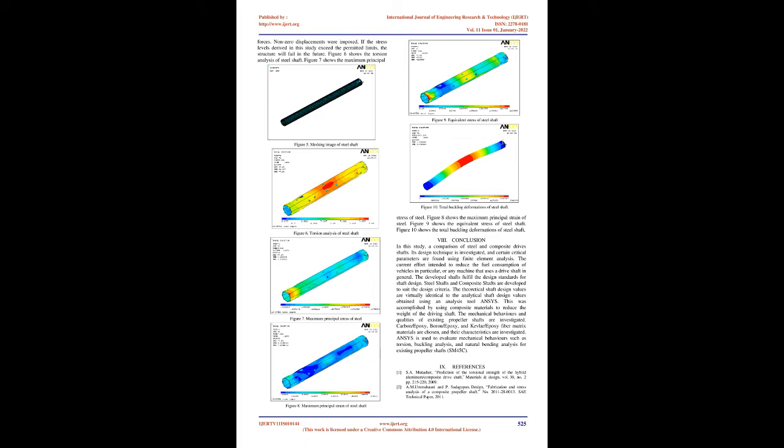3. Procedure for shaft material selection and proposed analysis. Because of their high specific strength and specific modulus, composite materials such as graphite, carbon, Kevlar, and glass with compatible resins are commonly employed. Composite materials appear to be an excellent choice for extended power driver shaft applications. The automobile industry is utilizing composite material technologies for the fabrication of structural components in order to reduce weight while maintaining vehicle quality and durability.